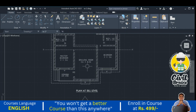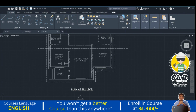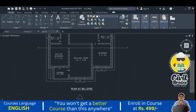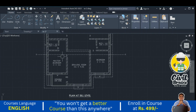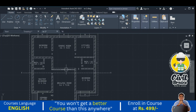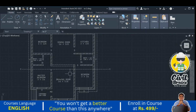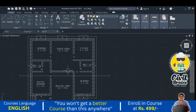Once you cut the building from here in the cross section and stand here, what all things will be visible, that we need to show. For example, we are standing here, cutting this section, and looking in this direction. If you cut this wall, you will see this one, and you will also see this background wall. This is the door cutting, and this dotted line will also be visible. We are considering this as an opening.